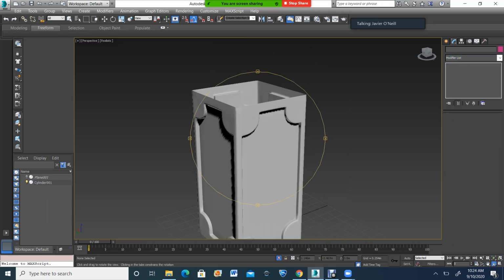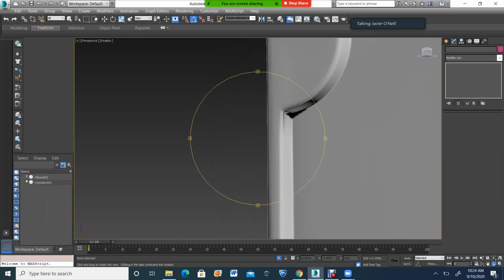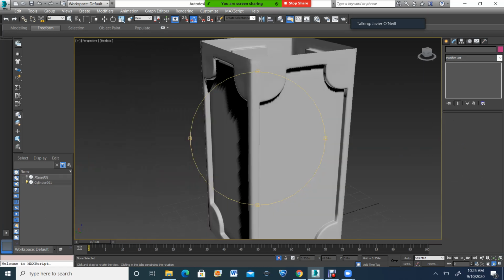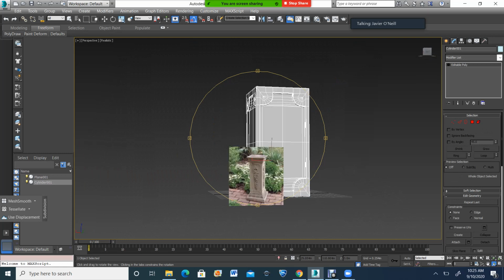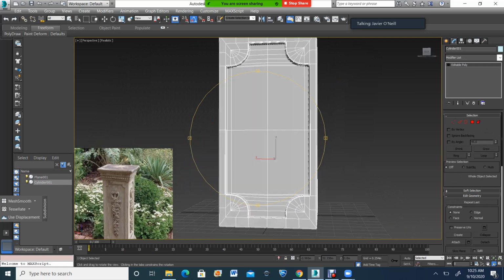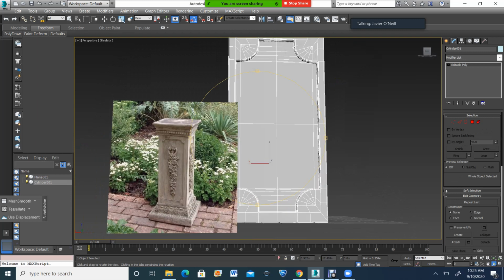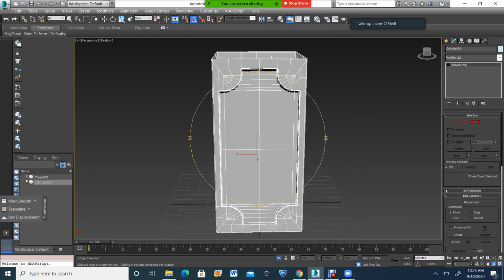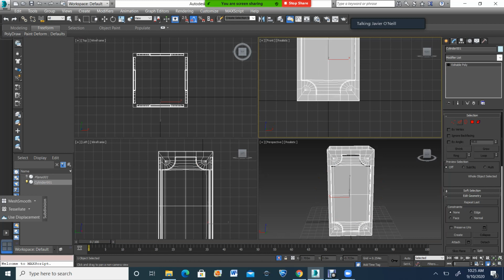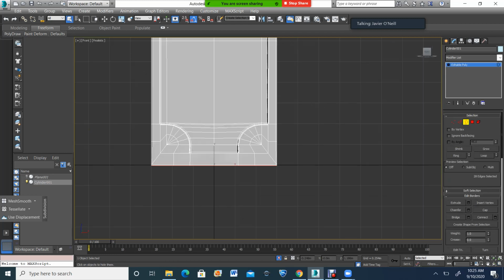And as you can see now, we are a little bit closer to that shape, so that is really fantastic. So I'm going to turn that off, and now we're going to start to build it upwards, because if I unisolate my mesh, as you can see, my reference has already exploded beyond the size it should be. So I'm going to start expanding this upwards and downwards so we can give it some of that shape. So I'm going to isolate this again down here. And then this one, I'm going to press 3 for border, which I didn't. Then I hold Shift, extrude it downwards, lock it, and then non-uniform scale like this.